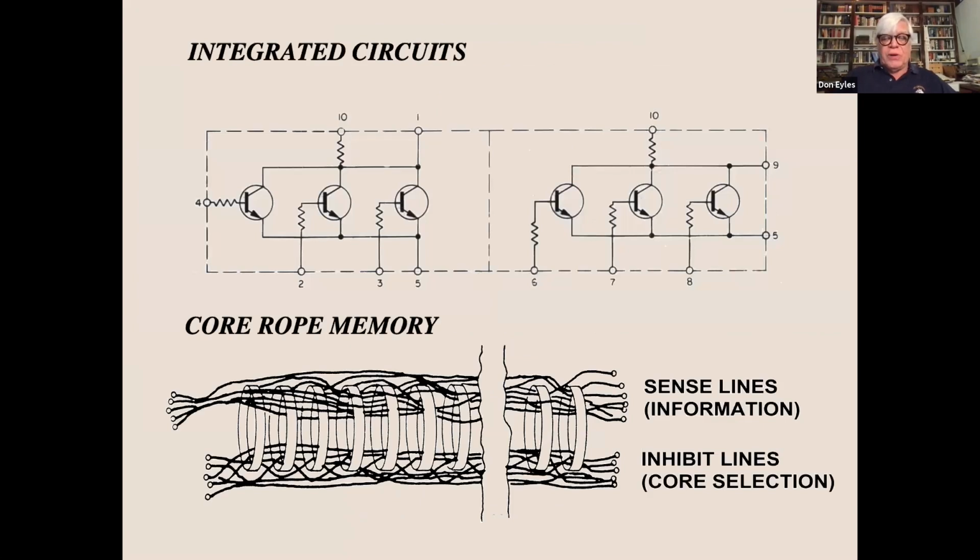Two of the things that helped it become reliable, not to speak of its other constraints, were the use of integrated circuits, which was extremely daring when it was decided on, because those were not at that time famed for reliability. But a lot of work was done with the manufacturers to improve the reliability and create enough of them for the computer and also for the peripheral ground test equipment. All used the same type of IC, which was a double triple-input NOR gate.